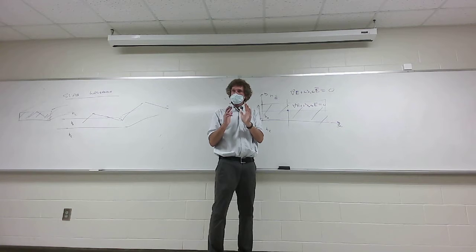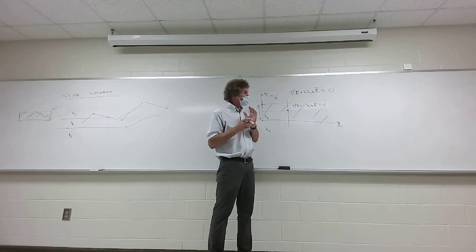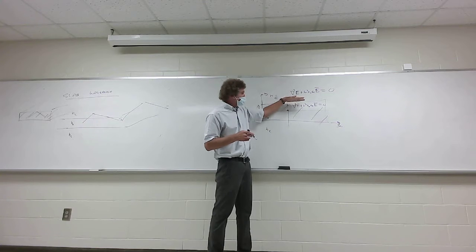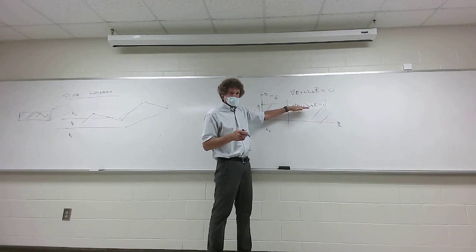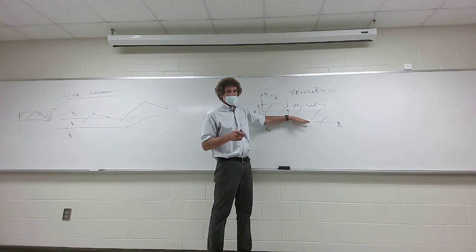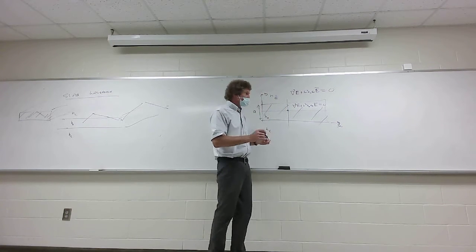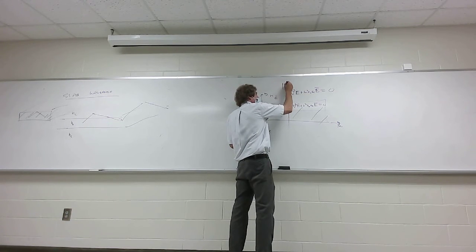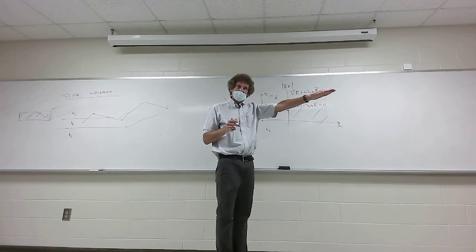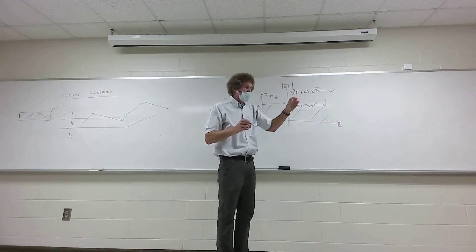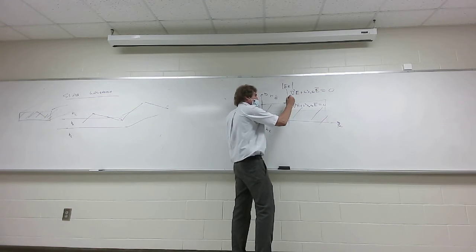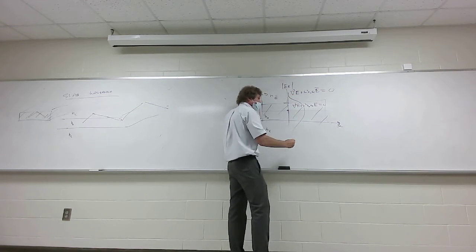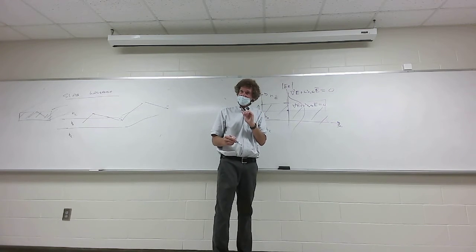Now, something that happens here, and this should be intuitively obvious. For this particular fiber, I'm talking about slab guide. That's where the light's contained, in this region, all right? It bounces around. In this slab waveguide, because the boundary conditions do not go to 0, if you would just look at the magnitude of EZ, if this is where the boundary is, and we just plotted, don't worry about writing this down, the magnitude of EZ. Remember, that's E field in the Z direction, in the direction of propagation. Well, it wouldn't go to 0. You wouldn't have a half-wave. What you would have is this.